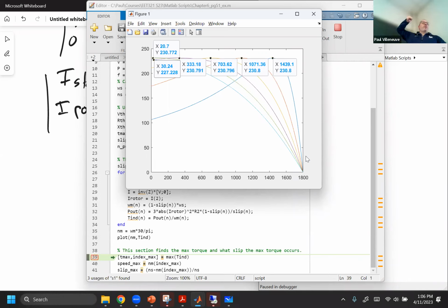So your rotor magnetic field and your stator magnetic field both spin at synchronous speed. And the rotor field is because you have an AC waveform that is induced on your rotor circuit, and its frequency varies. Remember the FR equation? It was equal to slip times your electrical frequency. So your frequency, I think we did a calculation, it was 1.8 hertz. Well, in wind turbines, instead of inducing it, they just put a three-phase variable frequency drive to put whatever frequency you want on the rotor.